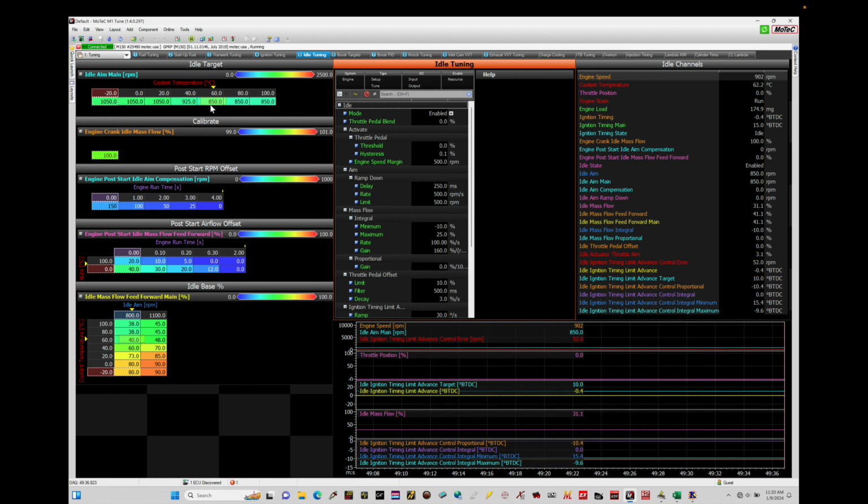So we'll find the fast path is generally what we prefer to try to manipulate in our idle control routine to get the engine torque output regulated to wherever the torque amount needs to be to hit the desired engine speed. So what we find here is that we have two different ways we can manipulate torque.